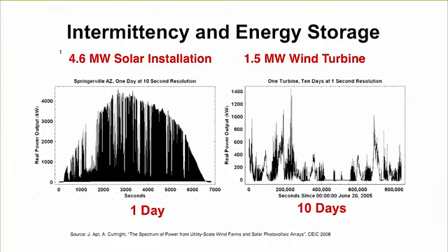We see the bump that would model the basic average, and then the intermittency from cloud coverage going over the PV system. So you could imagine that if I have a storage system operational, I can smooth out those high frequency bumps while also taking care of, for example, the duck curve larger picture function.